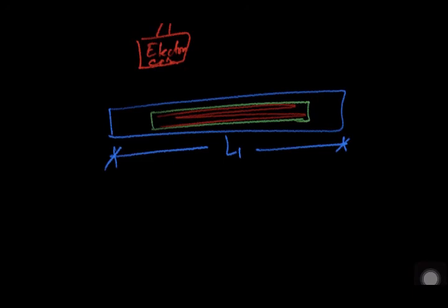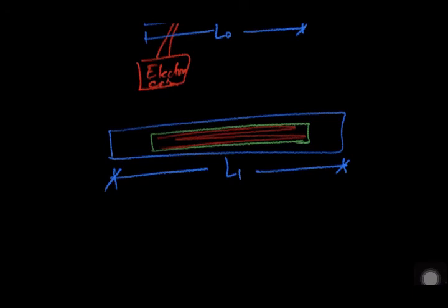And we know the concept of electrical resistivity. Once you stretch a wire, its electrical resistivity changes, and once the electrical resistivity changes, we are able to measure that change by these electronic circuits. And after that, there is a calibrated program, and accordingly we can calculate how much the resistivity has changed, and accordingly we can see how much the deformation of the body has happened. Okay, so this was all about the concept of stress and strain.